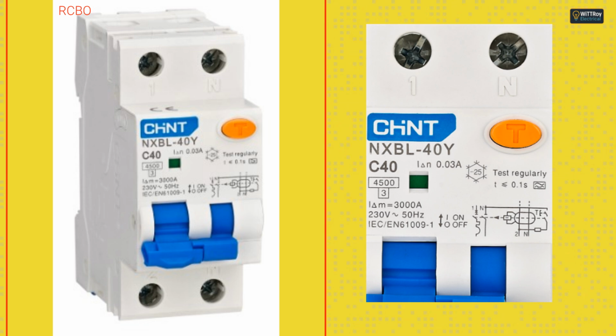Let's look at this device. I can see C40. C40 means it is a C-curve 40 amp MCB device. I can also see I delta N 0.03A type A symbol and a test button. That means it has 30 milliamp type A RCD protection.